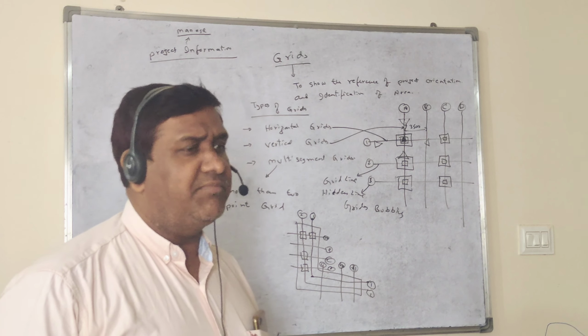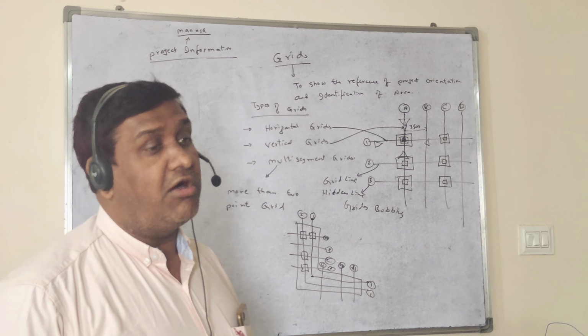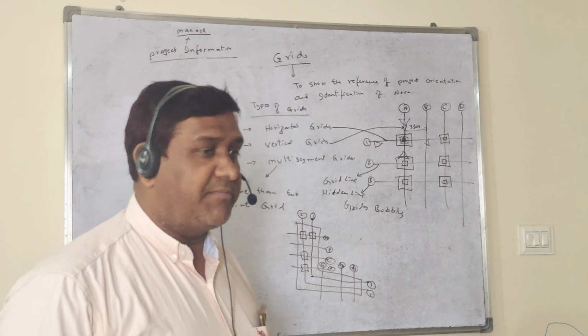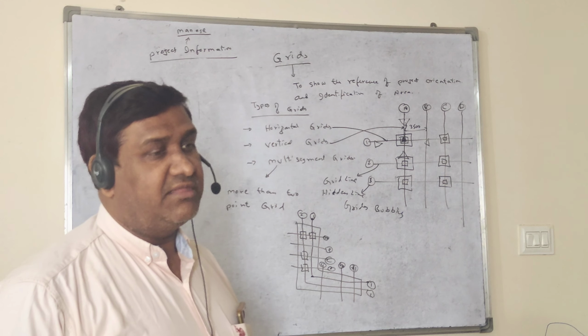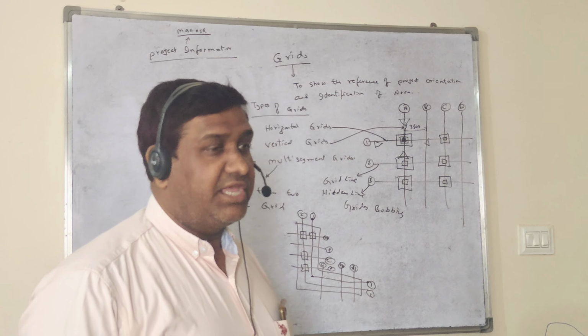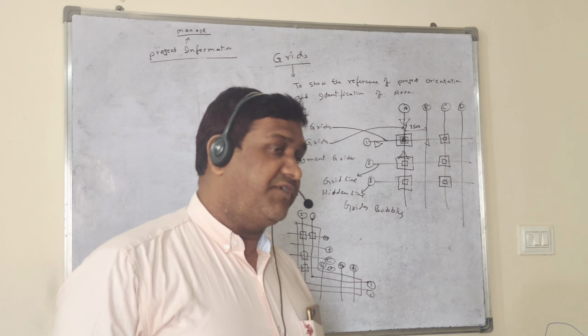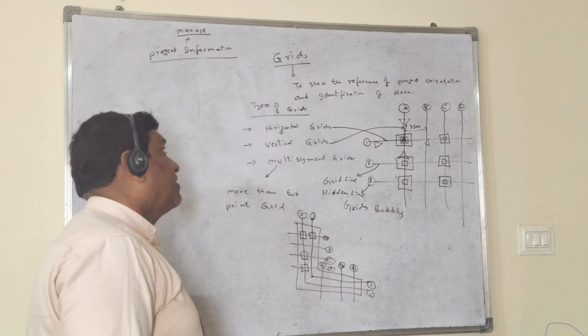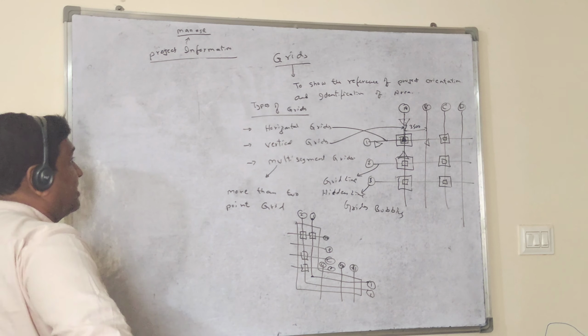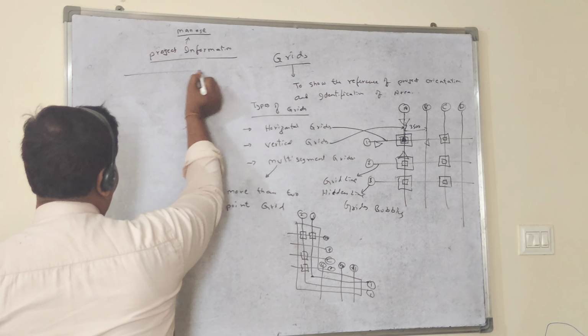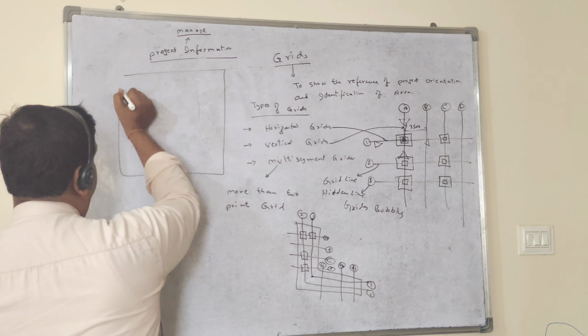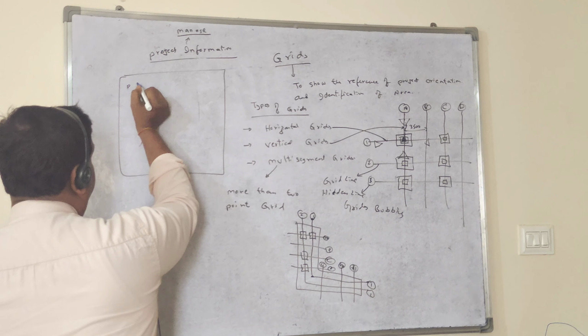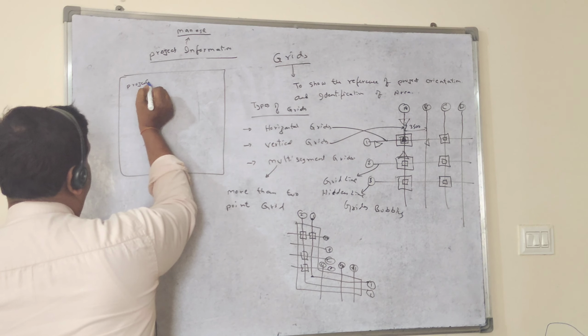Because right now we are working in BIM, we have to give all the information. So there is one separate palette that the Autodesk company has given. They have given some information fields that we have to fill in fully. If you click Project Information, one palette will open. In that palette, you have to give some information.